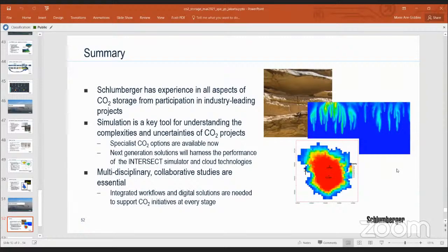So we have experience of injecting CO2 in the reservoir. As I mentioned, generally people have been using fairly simple vertical wells, but we are looking at design of horizontal injection wells in order to increase the volume going into the reservoir without too much increase in pressure. The kind of things we need to look at are actually the geomechanical effects and the integrity of the well itself.